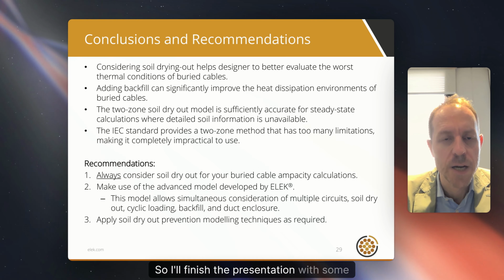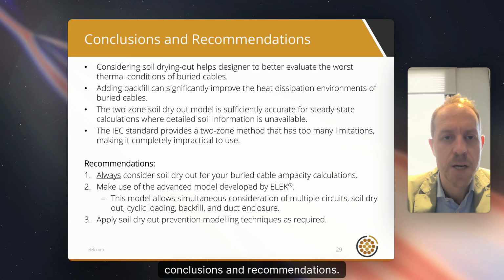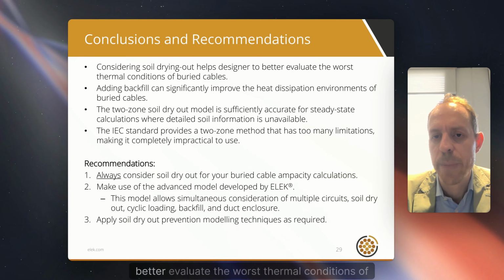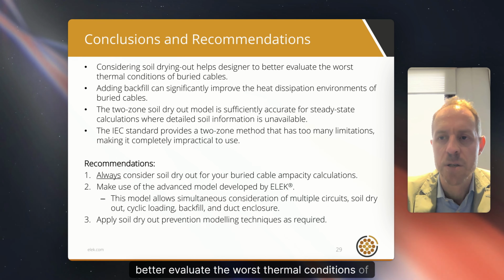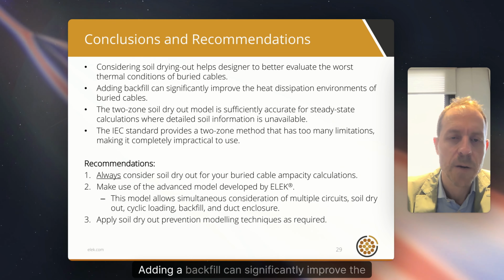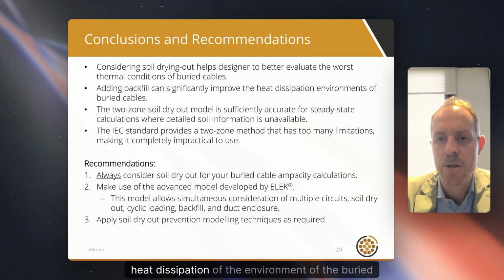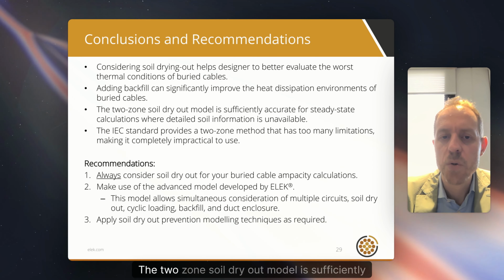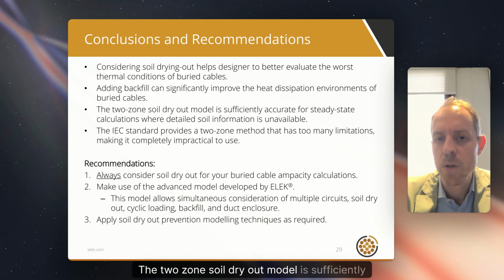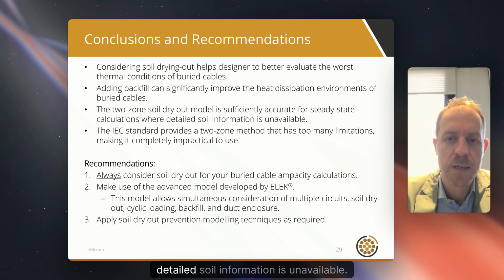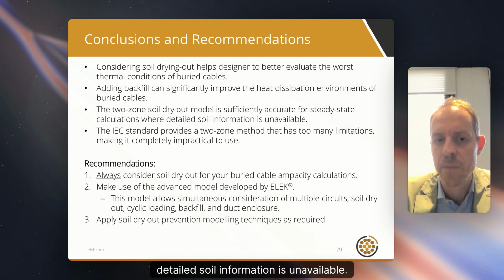So I'll finish the presentation with some conclusions and recommendations. Considering soil drying out helps designers to better evaluate the worst thermal conditions of buried cables. Adding a backfill can significantly improve the heat dissipation of the environment of the buried cables. The two-zone soil dry-out model is sufficiently accurate for steady-state calculations where detailed soil information is unavailable.